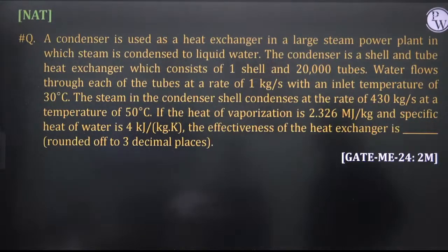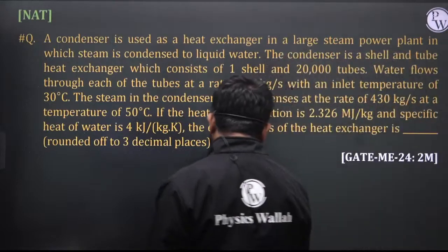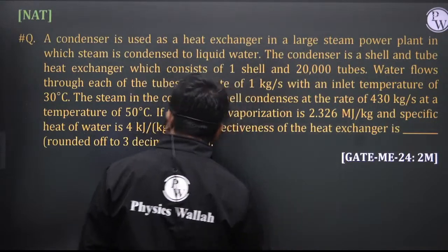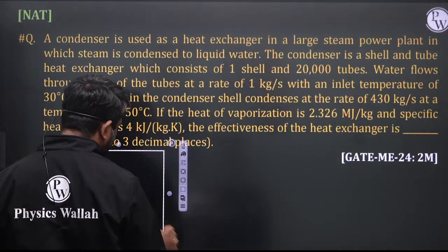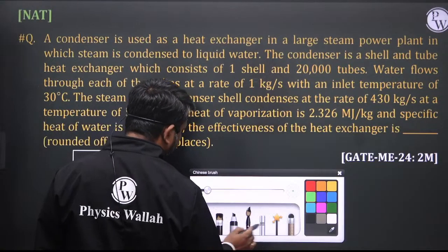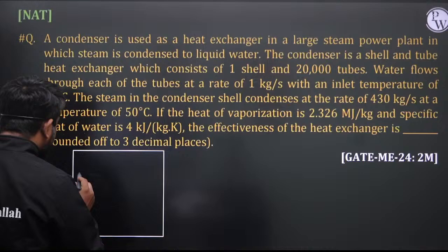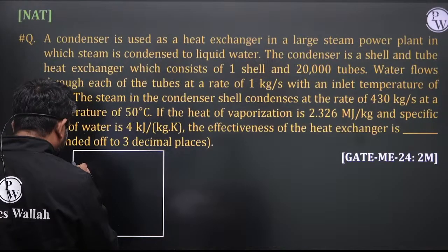Anyone? So this is a condenser type of heat exchanger, and whenever there is a phase change heat exchanger, the relative direction of fluid is immaterial.